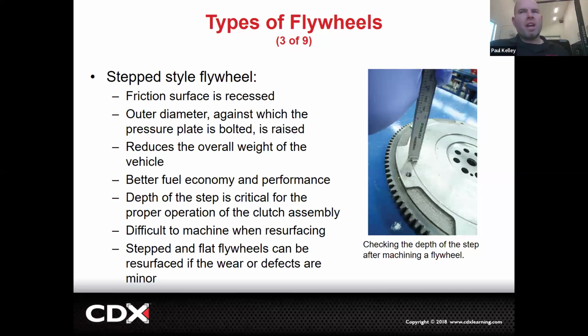The release system having air will not make it slip. The release system having a master cylinder, a slave cylinder, a line leak, a hose leak, none of that's going to make it slip. No. But if your adjustment is off and you release the pedal, but it's actually still disengaging the clutch partially because your adjustment's all jacked up, that could make it slip. And that's the only exception. If your adjustment is off where it's still releasing the clutch partially, even though your pedal's all the way up, okay? Log that in your mind because we're going to come back to that.